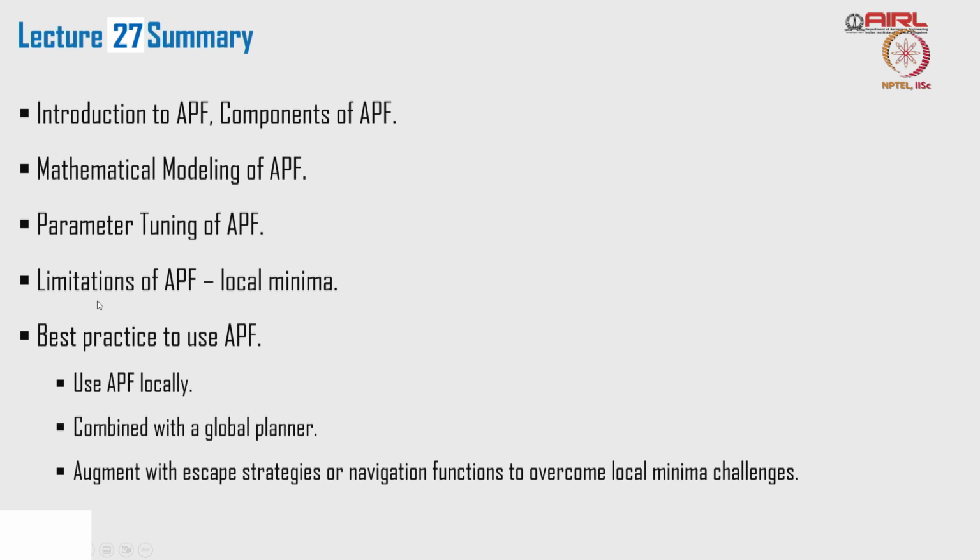We also discussed the limitation of artificial potential field, particularly local minima, and different mechanisms to avoid it. We also discussed best practices for using APF: when to use APF locally, how you can combine APF with the global planner, and how to augment the artificial potential field with strategies to escape local minima, which can be added into a navigation function. Thank you.